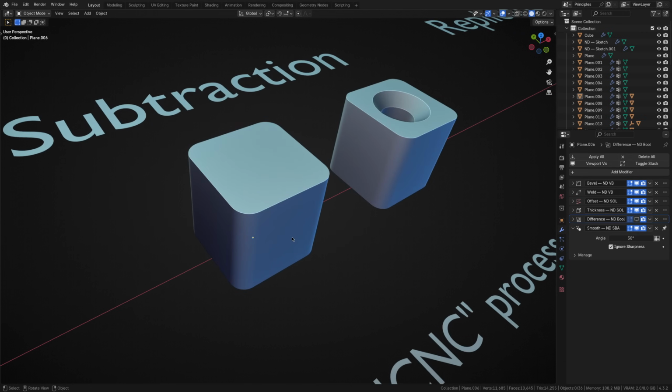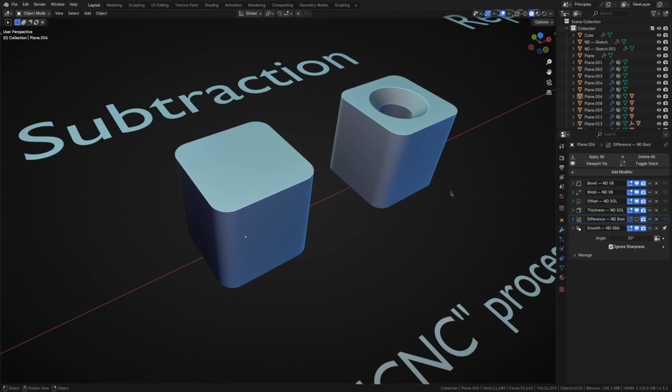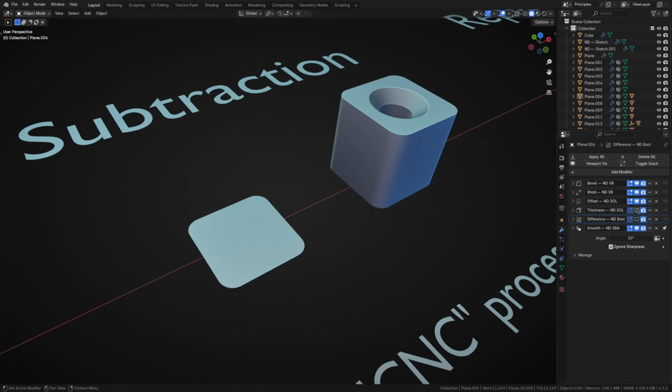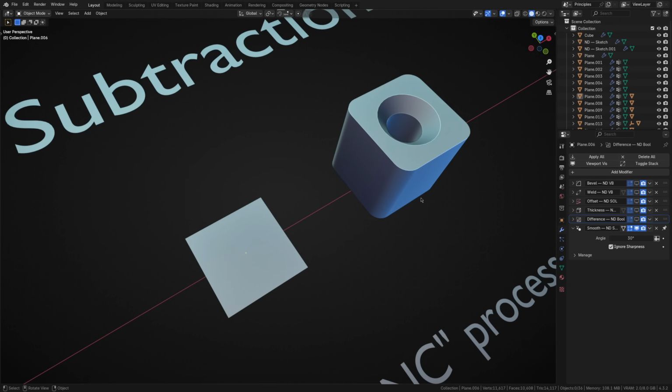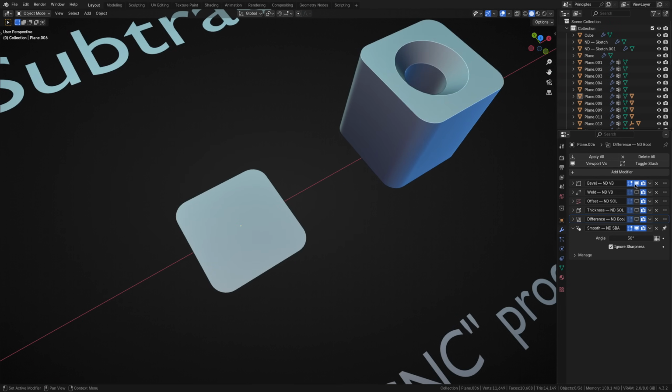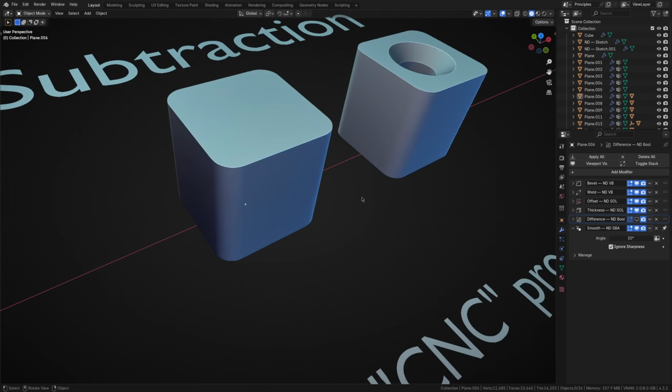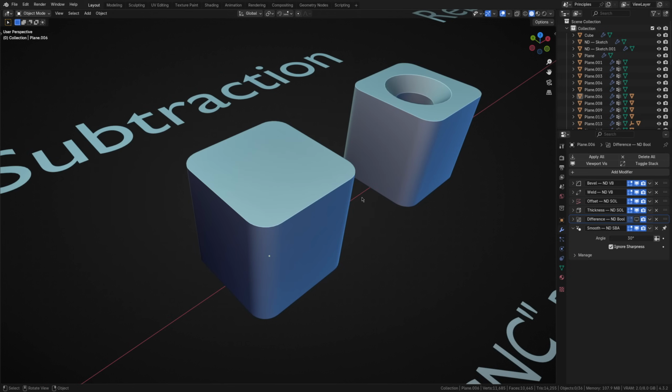So if you were given this final shape as a reference, you could deconstruct it in your mind back to a plane. And this is where you'd start. You'd then add the corner fillets, extrude the planar surface upwards, going from 2 dimensions to 3. Finally, you could subtract the final bit of geometry using a Boolean operation, leaving you with the desired final state.